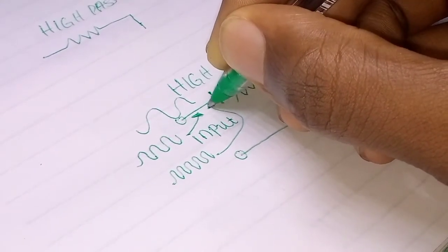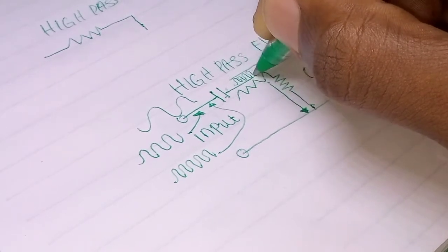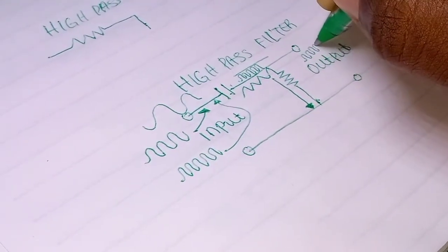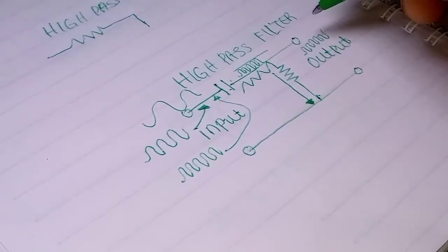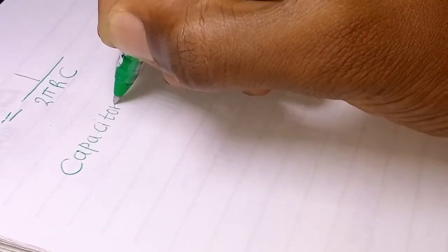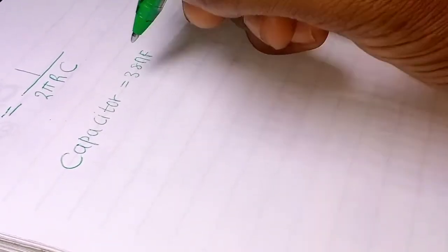Now, with the explanation of the operation of the filters, it's time to make actual calculations for specific resistor and capacitor values that will give specific operation. In my example, I want to calculate values for the low pass filter, which will allow frequencies of 0 Hz to 500 Hz to pass to the output, and anything upward should hopefully be blocked. And I'll calculate values to use for the high pass filter too.